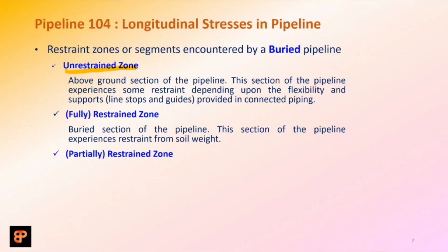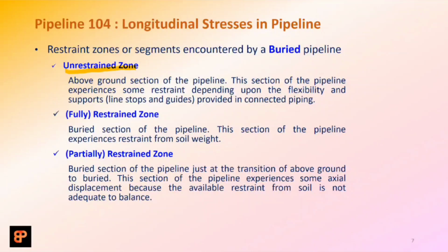The partially restrained zone, as I showed in the cross section, is basically the intermediate zone between unrestrained and fully restrained. Here the soil weight is acting, but for a certain initial distance the weight of the soil cannot provide enough resisting force against the displacement of the pipe.